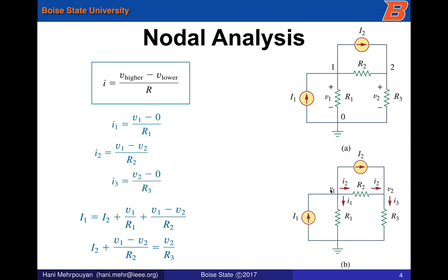We know what current is coming through here, which is I1, and we know what current is flowing through there, which is I2. Now, as we arrive at this node to try to label the current, we have to be very careful to remember that I2 is coming this way, the capital I2. However, this I2 that we placed here carries through this branch and arrives here. So we don't need to relabel this one as a different I. It's actually going to stay as I2. And we do need a new current label here, which is I3, because the I2 that comes here is added with this I2 to arrive at a different I, so that's labeled as I3.